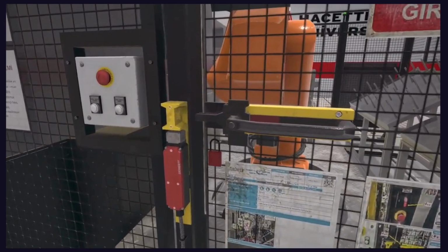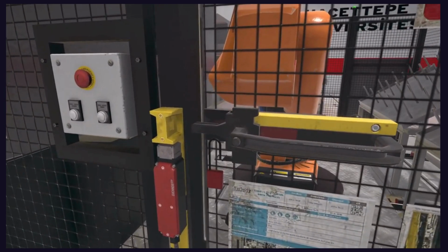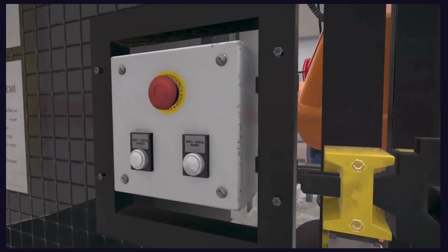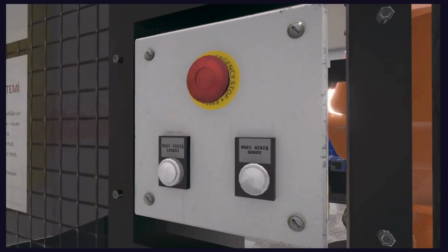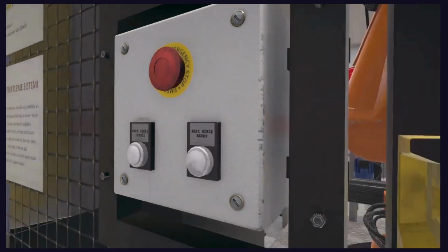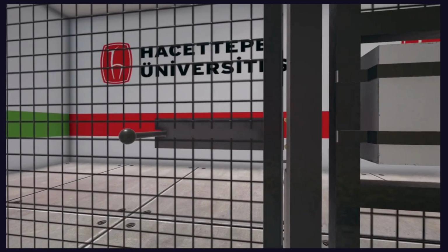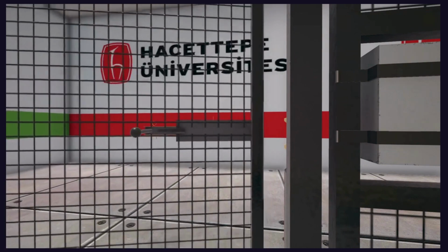After completing their work inside, the operator removes their padlock, reattaches the switch, and then presses the door reset button and locks the interlock switch. The operator starts the robot only after this procedure is complete. Escape function. The operator may forget to attach the padlock when entering the robot's workspace. Another person who is unaware of the operator working inside may lock the door. Hence, the door locks should be unlockable from the inside.